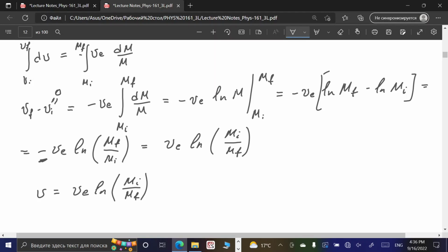Let's say it's quite possible for liquid type of fuel engine to use liquidized oxygen. So we cool oxygen to that extent that it becomes liquid, and then provide liquid oxygen in the rocket engine together with the fuel in order to get the highest possible oxidation inside this engine regardless of external conditions. Either we have atmosphere or we are somewhere in the space. Which challenges do you envision when we increase temperature and increase this exhaust velocity?